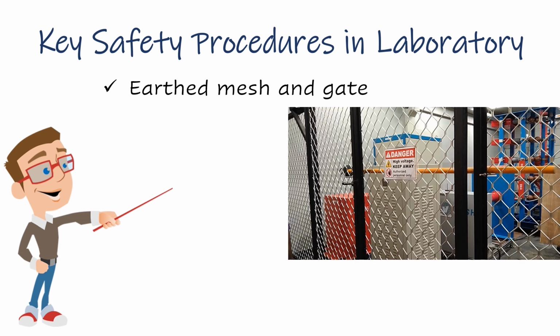After arranging all equipment for the experiment, the entrance gate is closed, and the earth rod is kept crossed. At the time the gate is properly closed, we can hear the sound of the limit switch. You can see how we did these safety procedures later in this video.